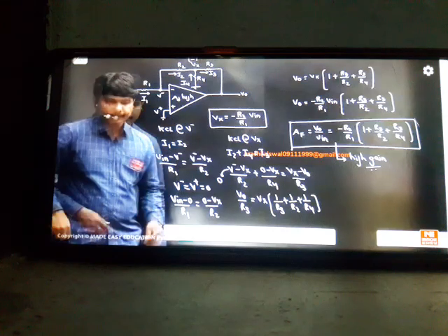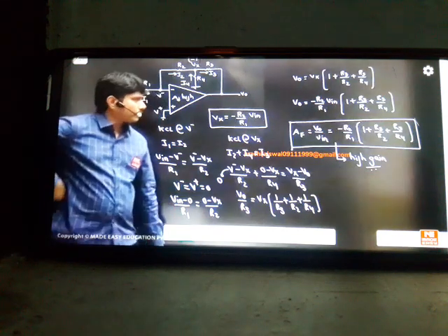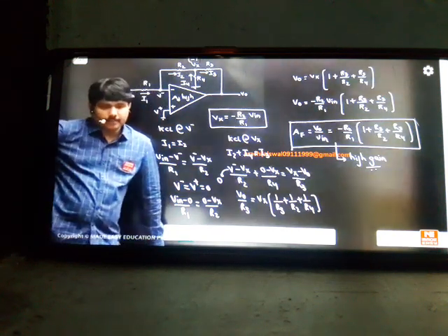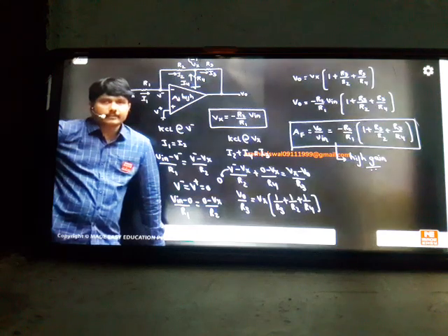T network techniques we have used without going up to mega ohms of resistance. So high gain will be achieved by this technique. That's why, from an exam point of view, whenever they ask you T network feedback questions, they'll ask you about gain. What is the voltage gain? The formula is this one.